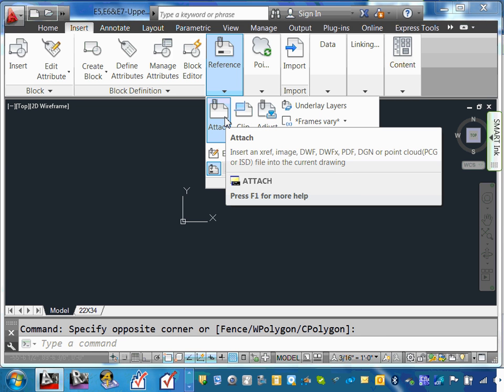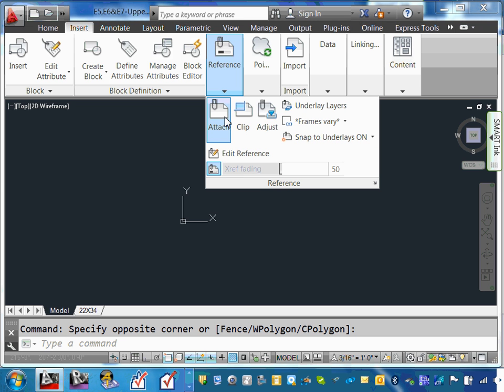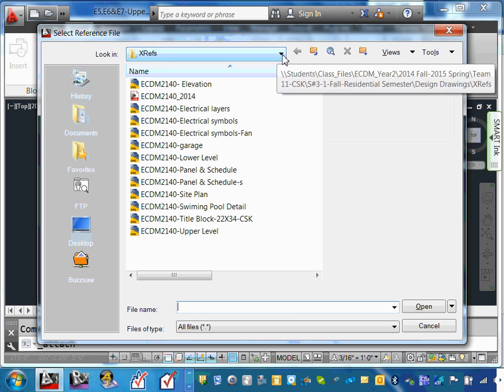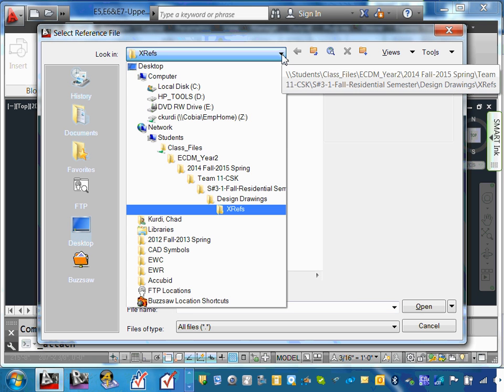Okay, are you with me? Cool. Okay, now I'm going to go Xref. Attach. Click attach. When you attach, it will refer you to the last time you did Xref. It will refer you directly into the last Xref that you did. Did it bring you guys there?